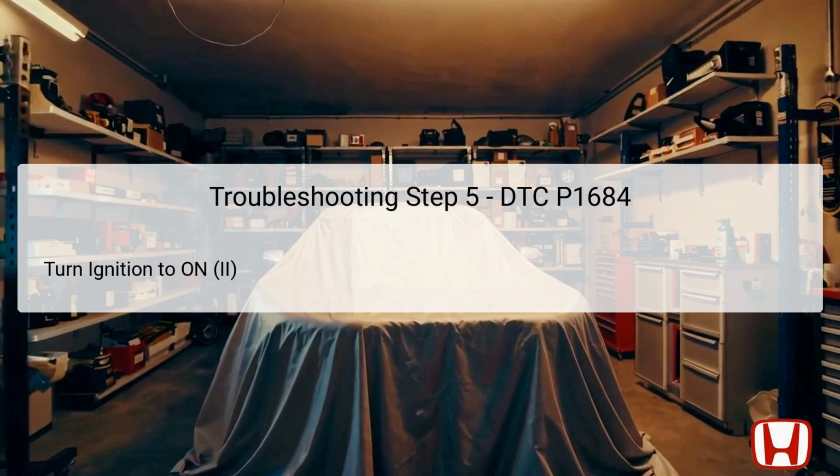After performing the necessary actions of shutting down the vehicle, the next step is to turn the ignition switch back to the on position. This reactivates the vehicle's electrical systems for another round of diagnostics. At this point, technicians will closely check for the presence of pending or confirmed DTCs using the Honda Diagnostic System, HDS.